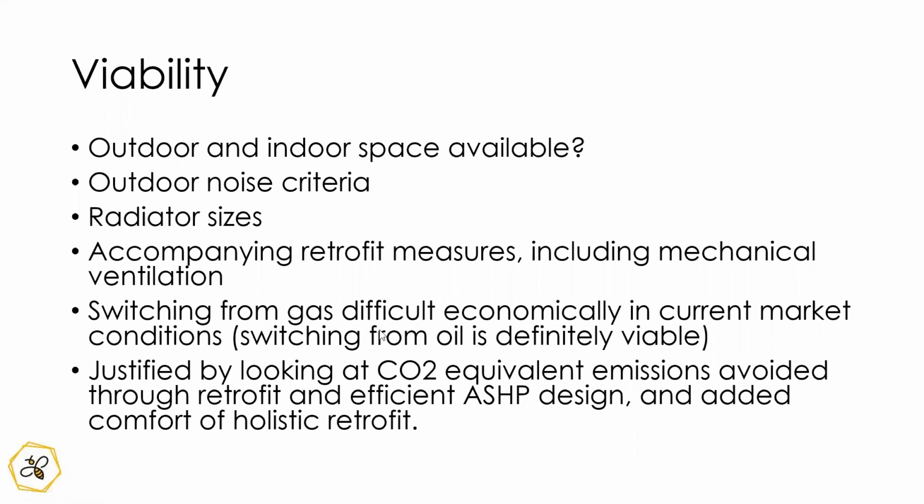Great. So your viability pointers are the same. I think we've been through this as well, but basically, have you got outdoor and indoor space available? Do you have noise criteria that you have to meet for planning? Your radiator sizes, have you included some retrofit measures to make it more efficient?